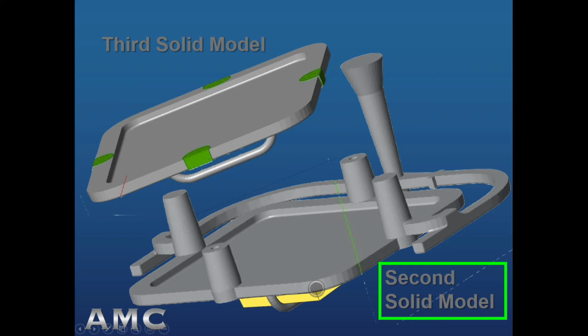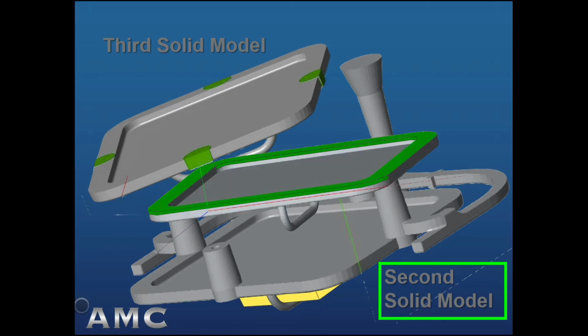All of the match lines for the top and bottom part of the mold, which will be across here in this parting plane, as well as match lines for core assemblies. Where draft is not allowed, additive manufacturing technology may be deployed to make mold components to eliminate draft. Machine stock has been added to as-cast surfaces that will later be machined to final net shape profile.